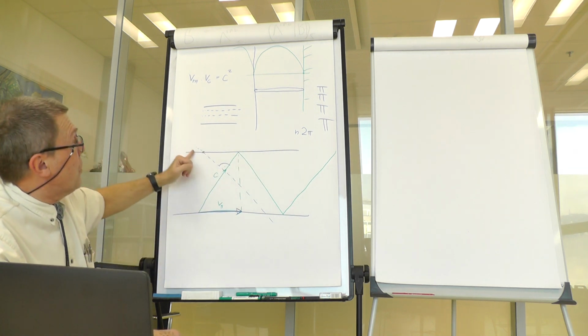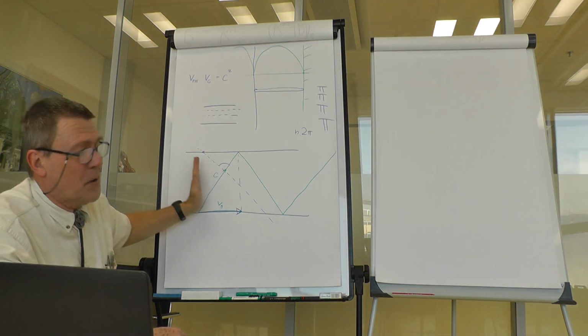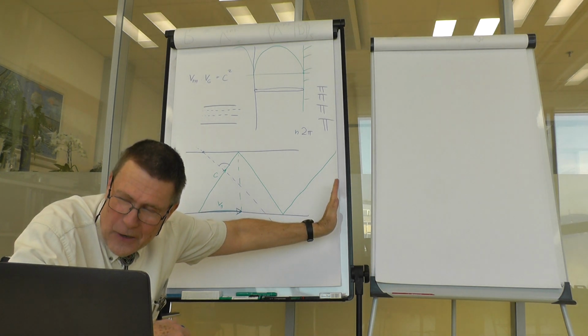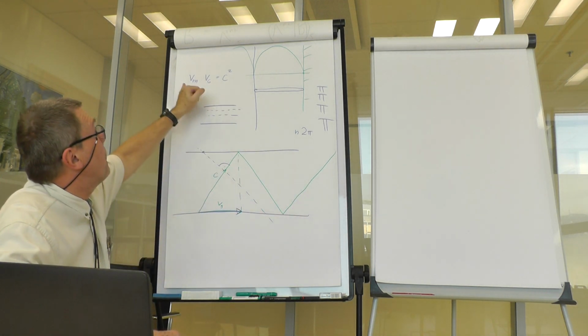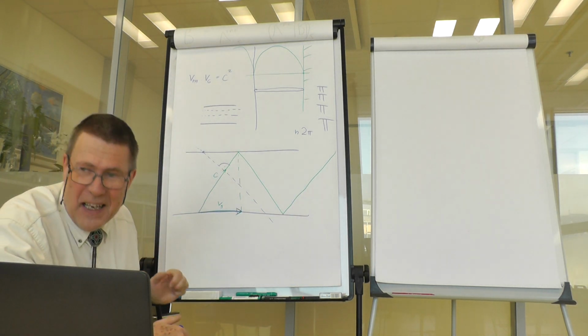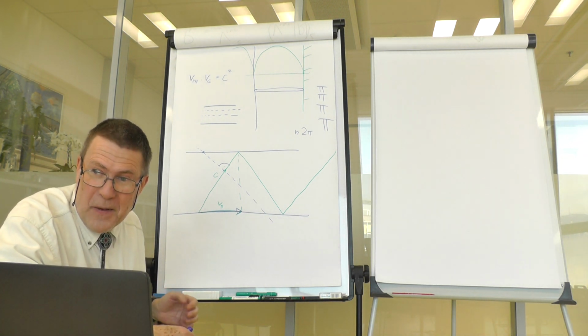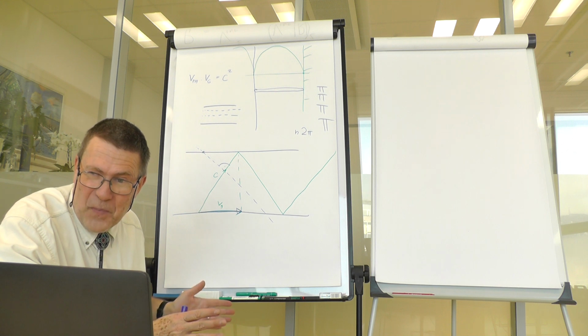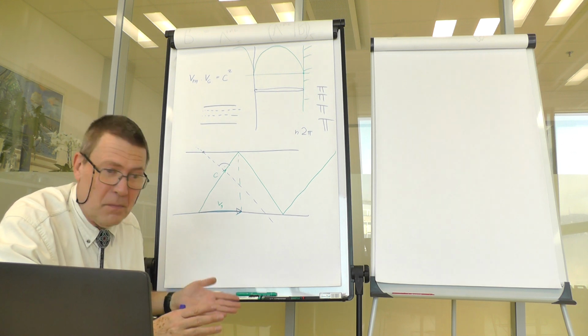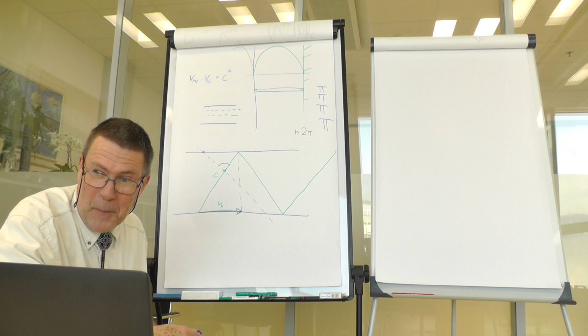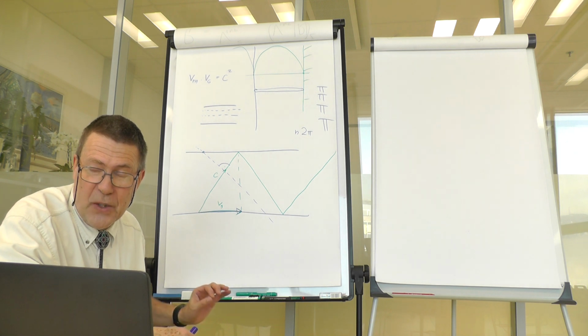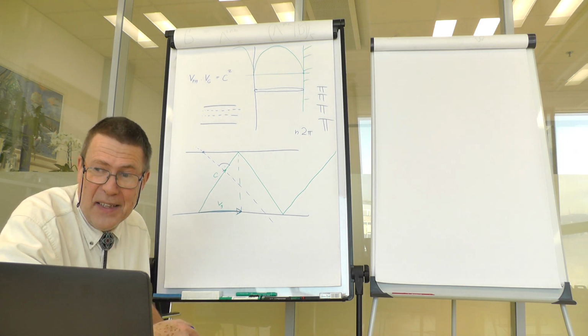And therefore the group velocity is important for propagating information and energy, but the phase velocity is important in order to establish lengths of the line for purposes like impedance matching. So we need to know both of them, and they differ.